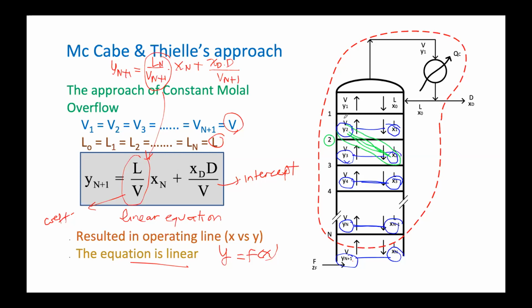Yeah. So this green line here would equal the correlation for the equilibrium. That's why, later on, if you know the equilibrium relationship using y and x, and you know the composition for equilibrium from the PTXY diagram, and then you know the operating line, then you can calculate how many equilibrium stages you need. Okay, I'm going to repeat it again later, but anyway, this is a concept.